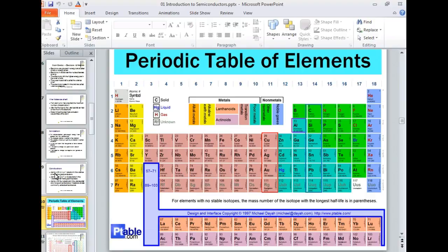Originally, aluminum's got problems. Aluminum has a big coefficient of expansion and contraction, so that means it really changes shape a lot when you heat it up and cool it down. So aluminum is hard to keep tight. I mean, it'll work itself loose. Another problem we have is that it oxidizes really fast. So aluminum oxide is an insulator. So they started to save money. They started wiring house trailers with aluminum.